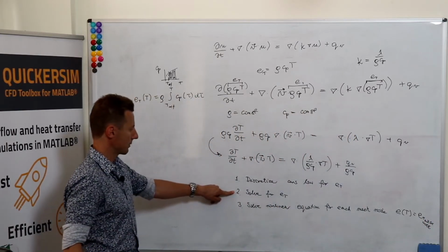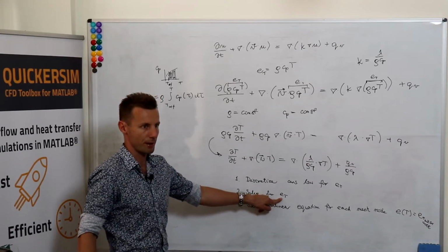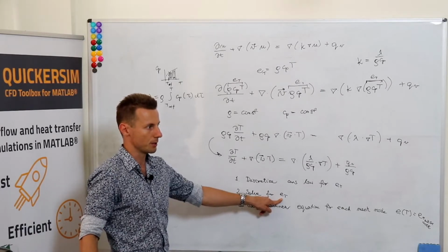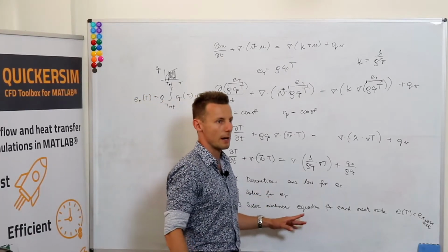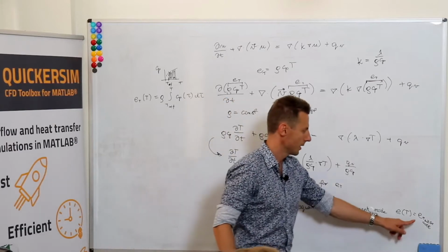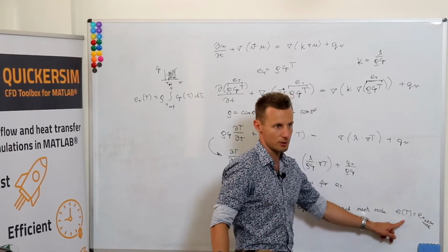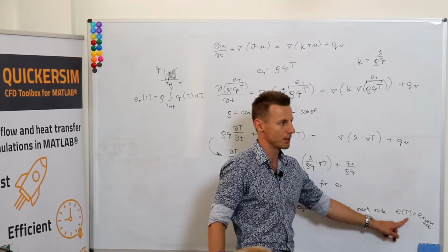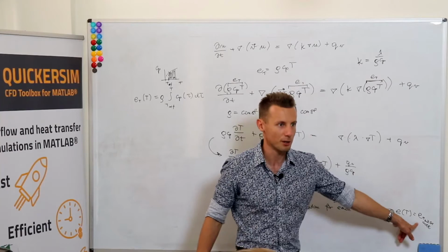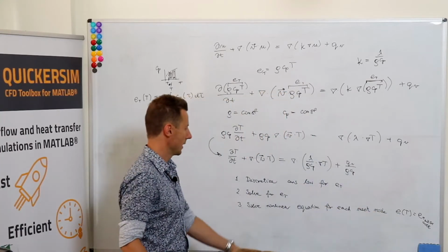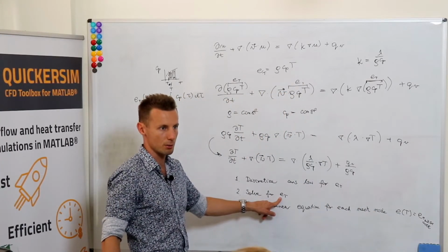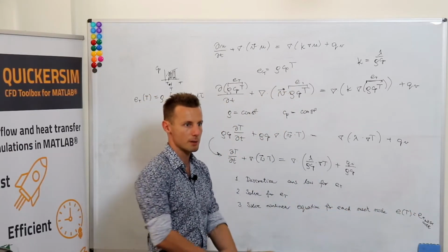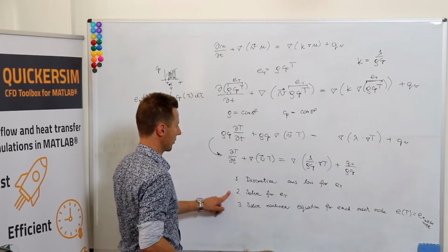So if you have solved this, you get the whole solution vector representing the ET value for each mesh node. Then, for each mesh node, you need to solve an algebraic nonlinear equation to properly select temperature T at the given node so that your energy really coincides with the thermal energy that you've got in your solution vector. By doing so, you retrieve the temperatures from the solution for ET.